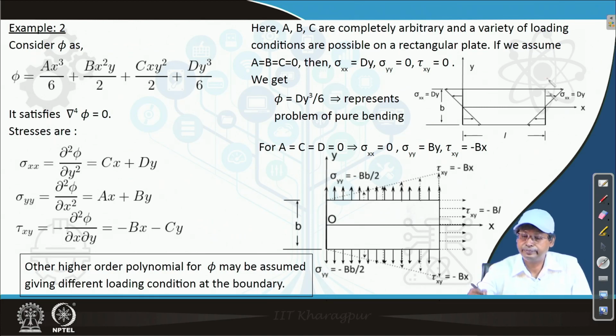d is varying. If this is the element we are talking about, half above, half below, then it is changing, representing a stress. Here it is tension, and in this part it is compression. Where do we get this type of stresses? We get it in pure bending. Pure bending means there is no change of bending along the length of the structure, and no shear force is acting.